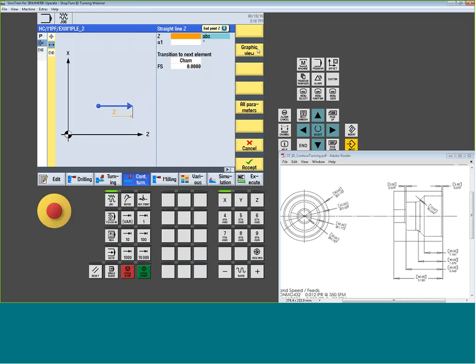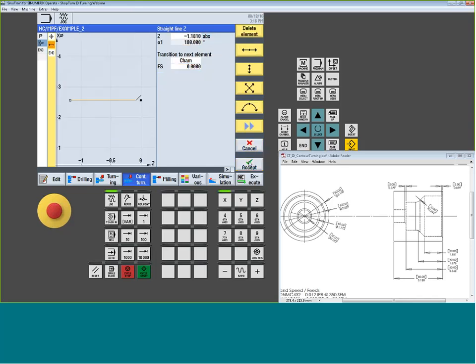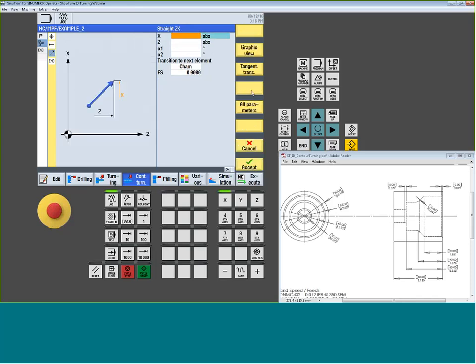Now we're going to roll around this part. So on the print, we move back minus 1.181. There's no transition, and this becomes the same as you guys have seen in other webinars. As far as plugging my data in, I'm just really picking the points right off the shape. So now we're going to do a 2-axis move to a 1.772 and a Z of minus 1.575.